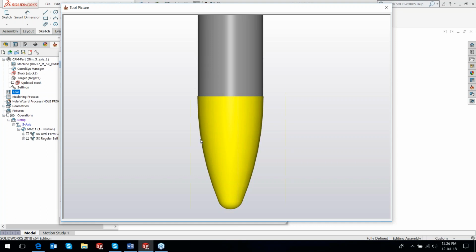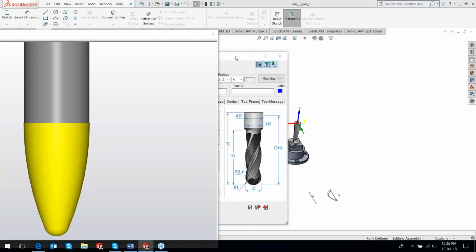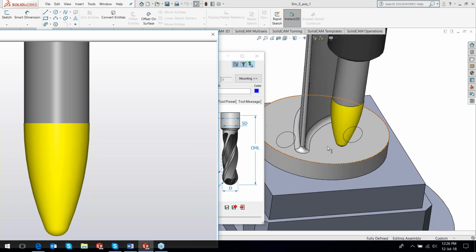as possible. Okay. Sometimes, if the geometry is completely open on both sides, it makes sense to keep the contact point somewhere in this region here. But if the geometry is closed at the bottom, like in this case, I have got the geometry that's closed at the bottom. Okay, it's closed at the bottom here. It stops. We need to stop the tool.